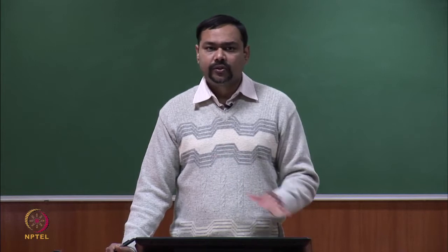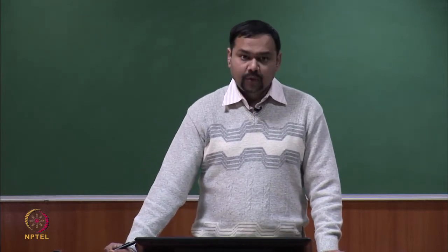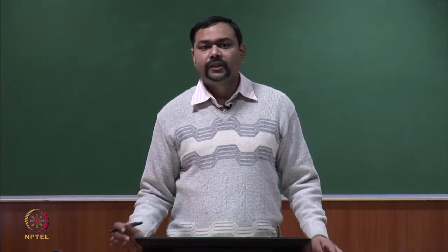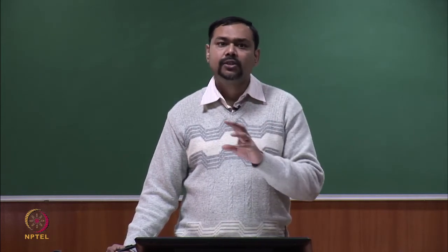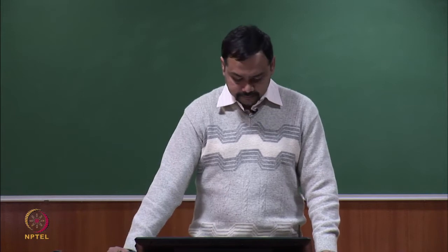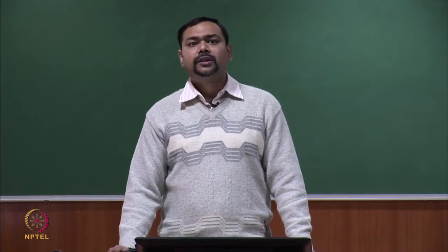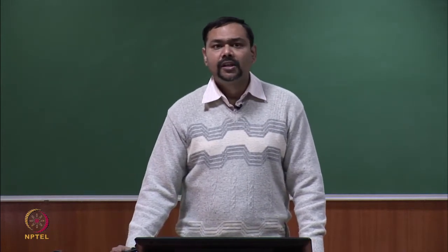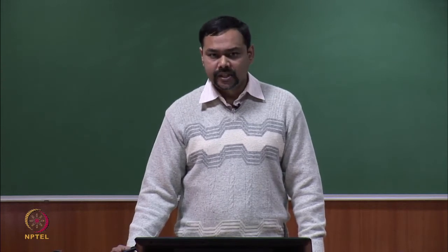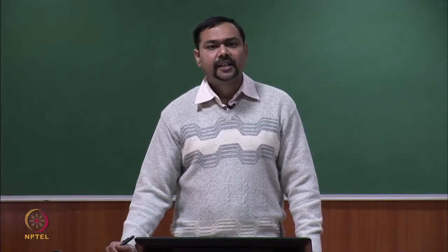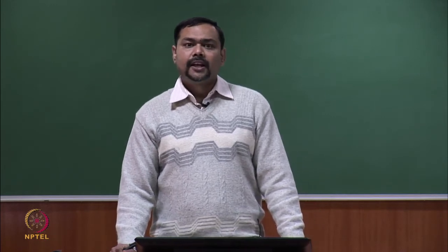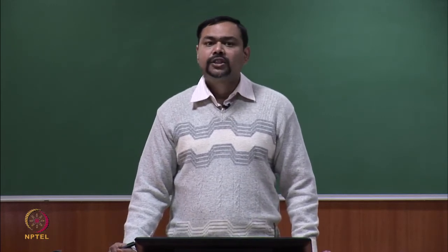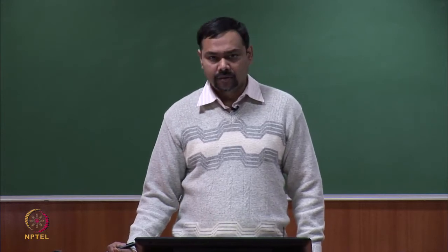This is how the structure looks. In this part of the course we are focusing on the rectification part, that is AC to DC. What has been popularly used for converting AC to DC is a 6 pulse, 3 phase bridge rectifier, which has been a very popular choice for a long time now.